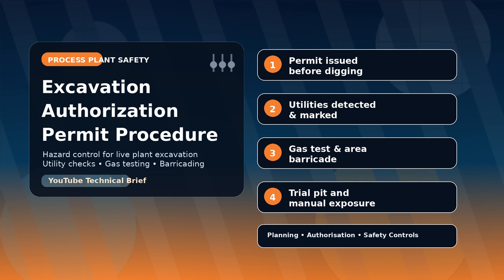Sometimes they may also ask to attach the method statement or procedure. What the hazards are, that also you need to mention in that permit. There are a lot of hazards, maybe I will cover those in a separate video. There is a possibility that you need to barricade those areas, because an unknown person may fall into that pit and get a fracture or injury.